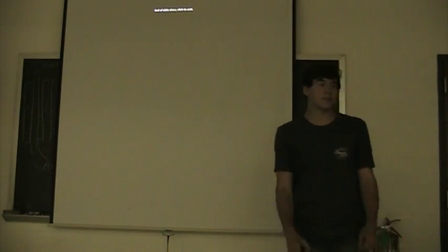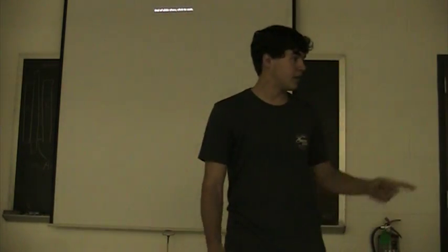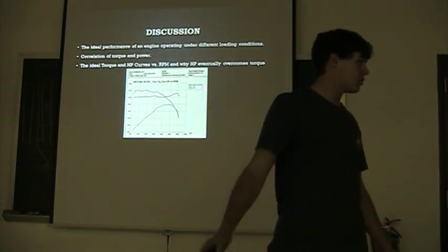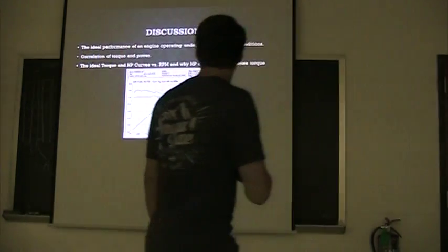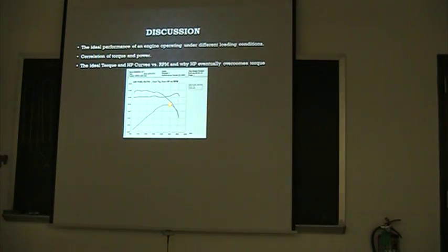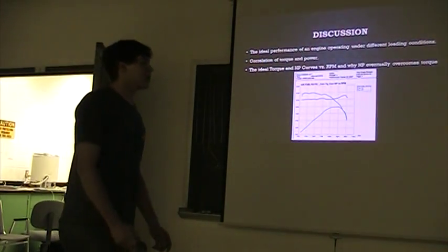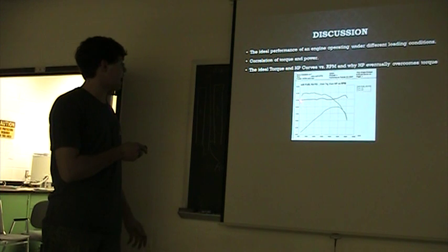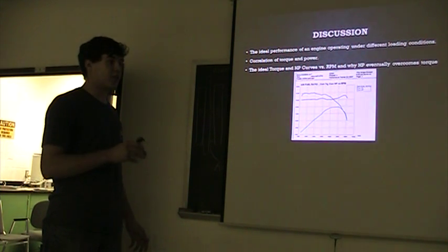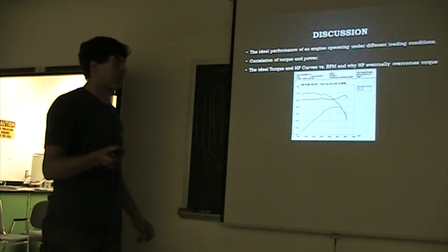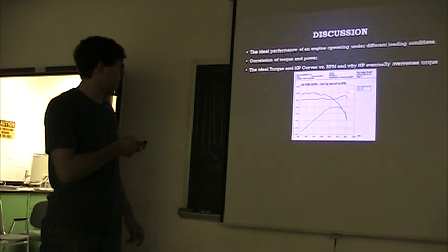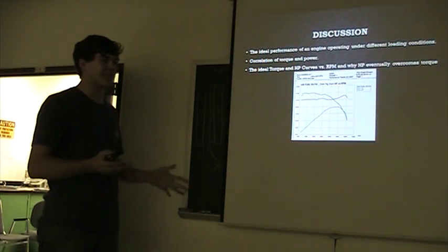And that's it. I have a question for you. Yes. So that's horsepower, torque, graph. So what's the third line? Oh, this is actually the air-fuel mixture right here. You want to keep it usually between 12 and 14. 14 is a little lean. 13 is fine. So this just, as you run the motor, it will change with RPMs and the tuning of the motor. And that's why we see like a little lip over here. You want to keep it as constant as possible, but it's not always possible.